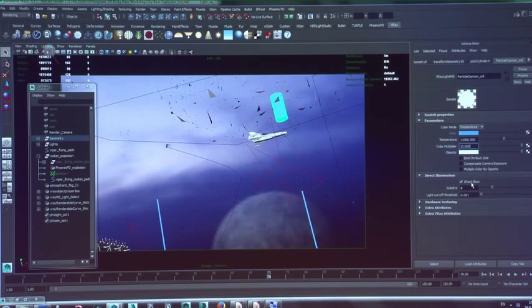If I turn that on, I'm not going to rely on the GI calculations to see the effect of the light material propagating light in my scene, but V-Ray is going to emit direct lighting for each and every mesh that has this shader applied. This is not going to be GI. And this is a really cool thing, because I'm going to show you why in just a couple of seconds, but this is really important when optimizing your scene for rendering. I'm going to turn that off for the moment.